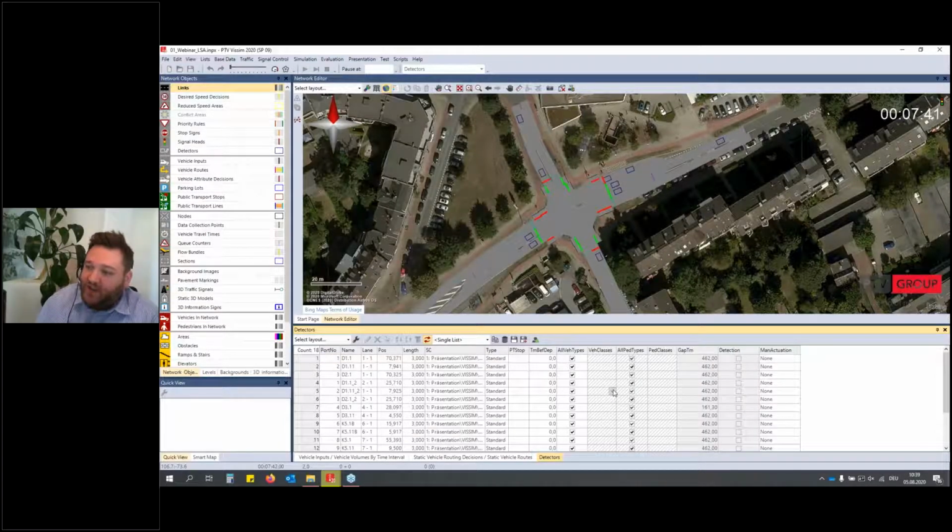If we now select the same detector, which in this case is the detector D3.1, we can select a repeated or continuous detection here. And in this case, there should be a detection whenever the road has a red signal, and the signal control should switch back and forth between the two stages.